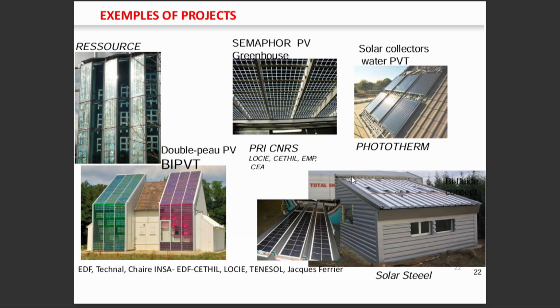Why southeast orientation? Because it was an existing building. We want to demonstrate that one of the constraints of an existing building is that the structure is not really designed to accept a new weight, and also that the orientation was chosen a long time ago, and you can't turn the building. So we want to show that even if the facade was not fully south, there is some nice aesthetic adaptation that could allow to optimize the orientation of the PV.